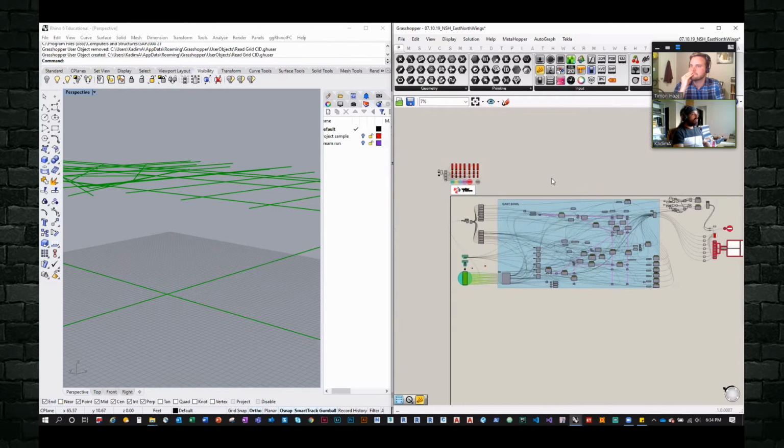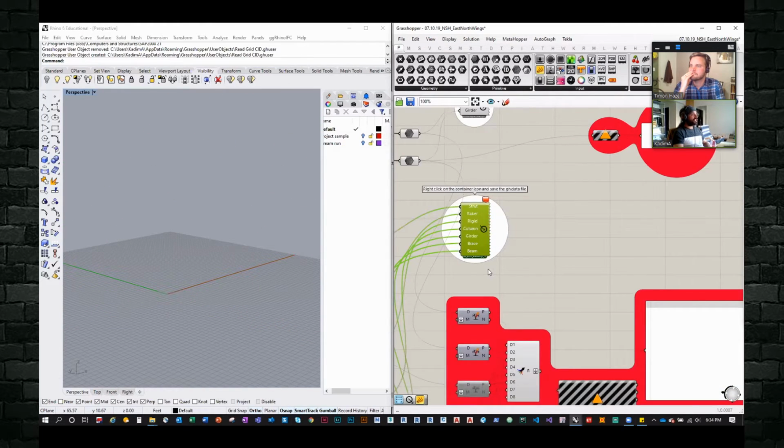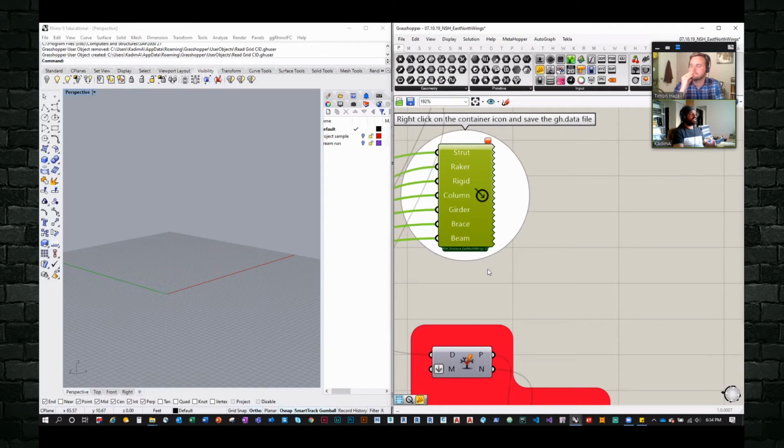And then we're all exporting to a shared stored file that gets referenced in an overall file that builds the entire stadium. Gotcha, so they all get parsed out and then brought back together. Exactly. So we all have the same starting point: the same data set, the same grids, same levels, same divisions, same indexes. And then we go to the same spot. But in between, we have our own creative autonomy in how we set up the script, what clusters to use, how to connect them, and so on.